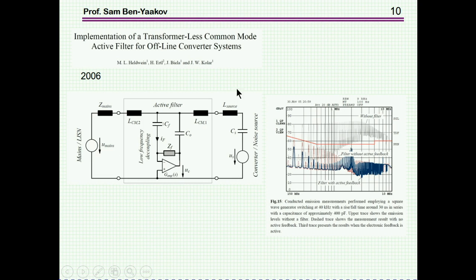This is the noisy part, and some of these impedances are the parasitic impedances. These are the impedances that are added on, and they are used to attenuate the ripple voltage or absorb the ripple current. Now here they're showing the noise level before adding this active filter. Here it is, and this is after adding the filter.